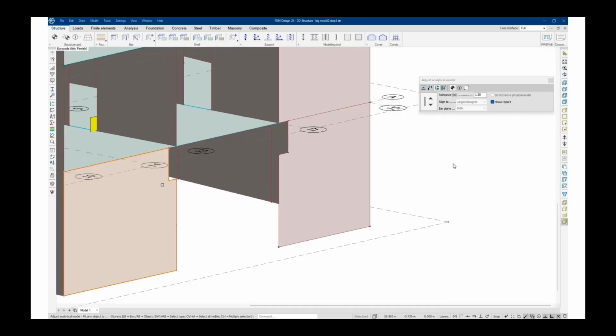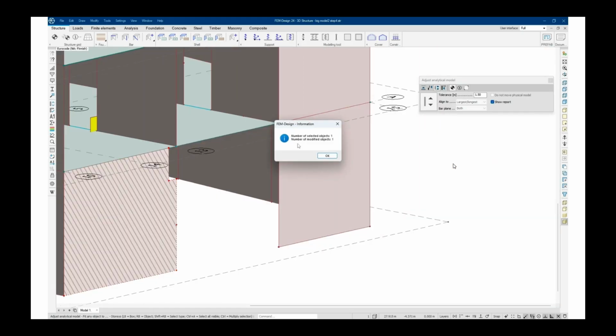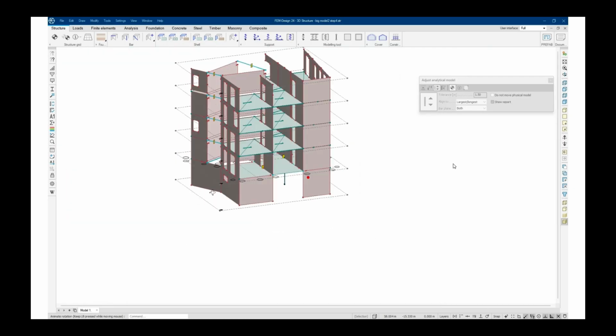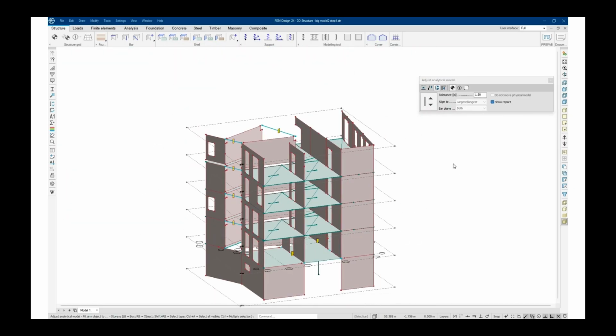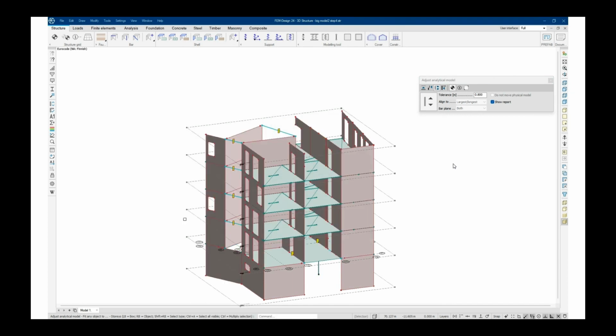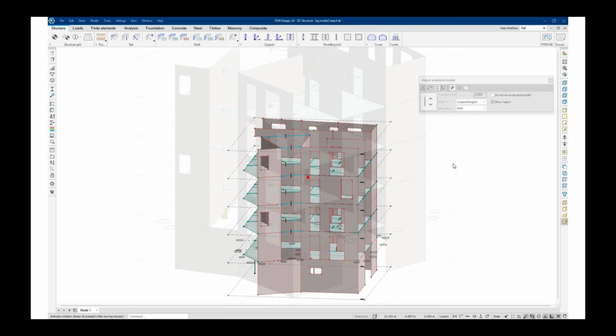will be gone like here. And also there, so the edge will be stretched to the story level, and now they are gone. So it's handy if you have a big model, you can fix like 30 walls in just like 1 second. And we can probably run it for the whole model because it's a pretty safe operation. Usually it doesn't do any harm here.